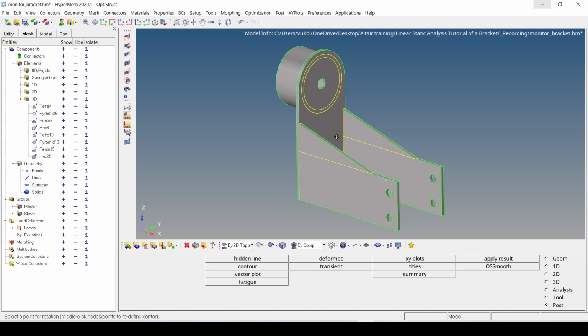Now we are going to speak about how we are going to modify our model so that when we later on create a solid from surfaces, only one solid is created. In order for one solid to be created, we cannot have any of these yellow lines which are shown in this picture. This is because this means that we are going to have multiple solids created from surfaces.